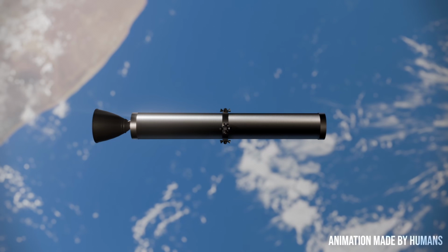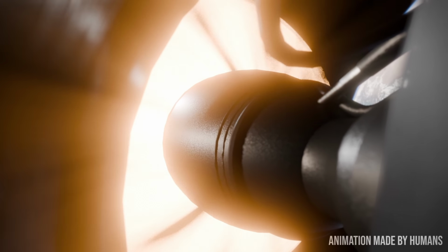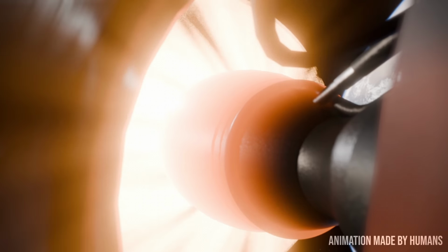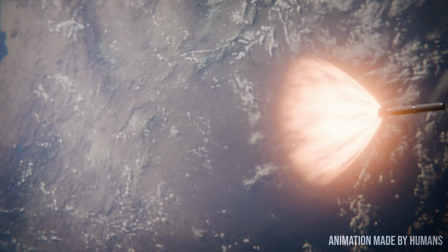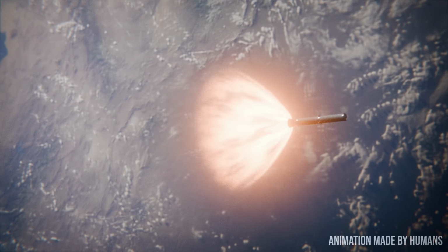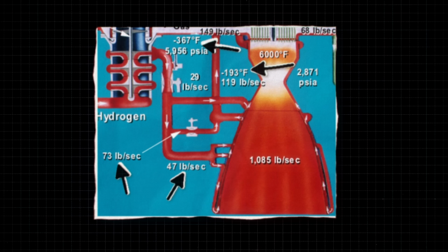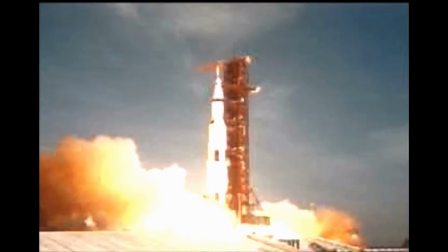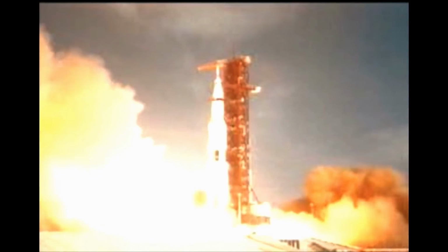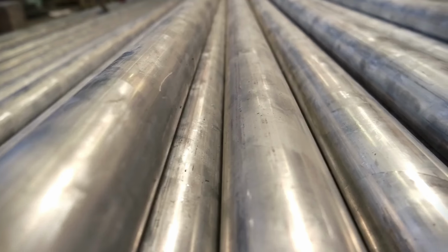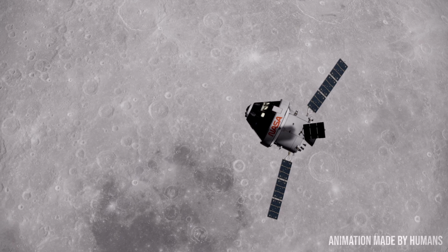And then the second mission characterizing figure, thrust to weight ratio, can be thought of as the acceleration requirement, how fast it needs to spend that delta V, or rather the mass flow rate the rocket needs to be capable of. And it mostly determines what kind of engine is needed, which is mass flow rate, engine size, tank pressurization, structural loads, and thermal demands, that sort of stuff. Of course, these are not the only numbers needed to fully design a rocket. We still need to know things like propellant choice and materials like aluminum or iron or titanium or steel, but all of those things live downstream of delta V and thrust to weight ratio, and are mostly going to be dictated by our ISRU bill of materials.